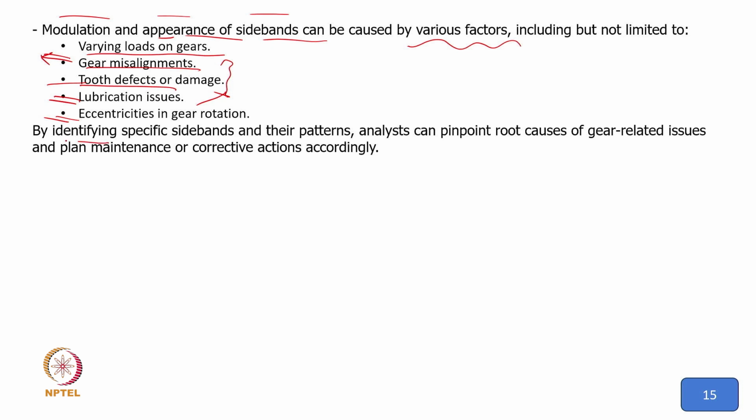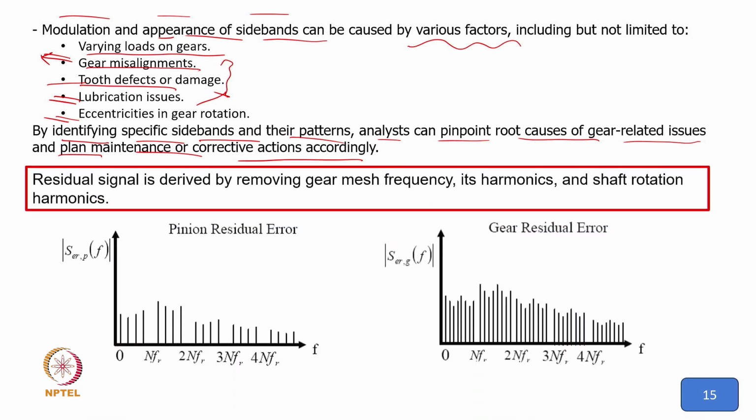So what we say, by identifying specific sidebands and their pattern, analysts can pinpoint the root cause of the gear related issue and plan maintenance or corrective actions accordingly. So it gives us information well in advance.